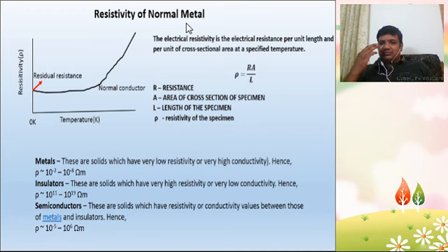If the temperature of the material is increased, the lattice vibrations become more pronounced, so more scattering events take place. Because of the more scattering events, the dissipation of heat will become more. So, this property of the energy transfer from the kinetic energy of the electron to heat energy, and in that way the decay of the current, is called resistance.